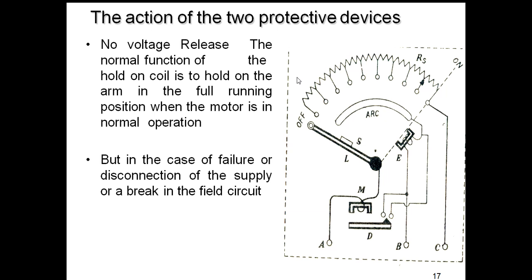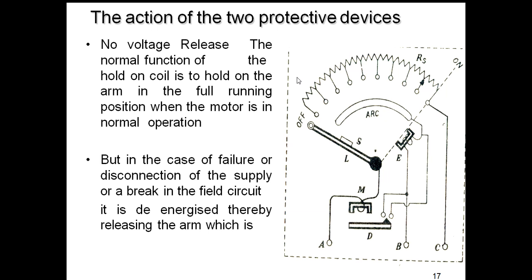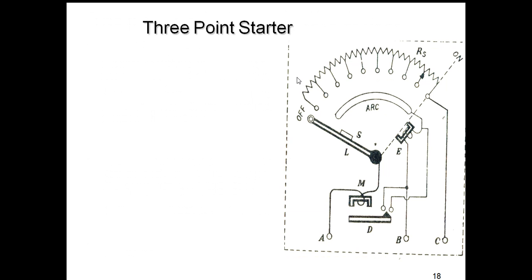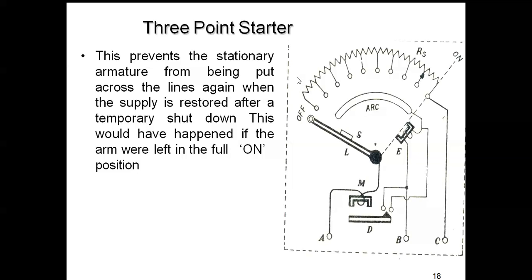But in case of failure or disconnection of the supply or a break in the field circuit, it de-energizes, thereby releasing the arm, which is pulled back by the spring to the off position.